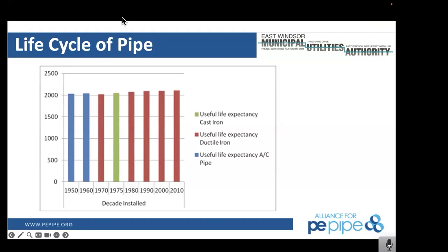Not only that, I've worked in communities that had wrapped ductile iron pipe, and when you have a break, you're chasing it, because it expands into the bag and then finds the path of least resistance, which could be a rip or a tear 20 feet up the road. So you end up chasing it, and it costs you more in the repair of the road than it does in the repair of the main.